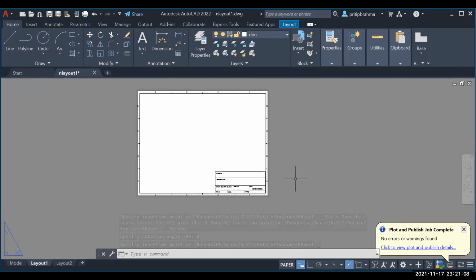So this is where we start, right? This is our drawing format. We could also insert our tolerance block right next to this, and those are for tolerances we don't specify directly in the dimensions. So now what we want to do is insert what are called our viewports.